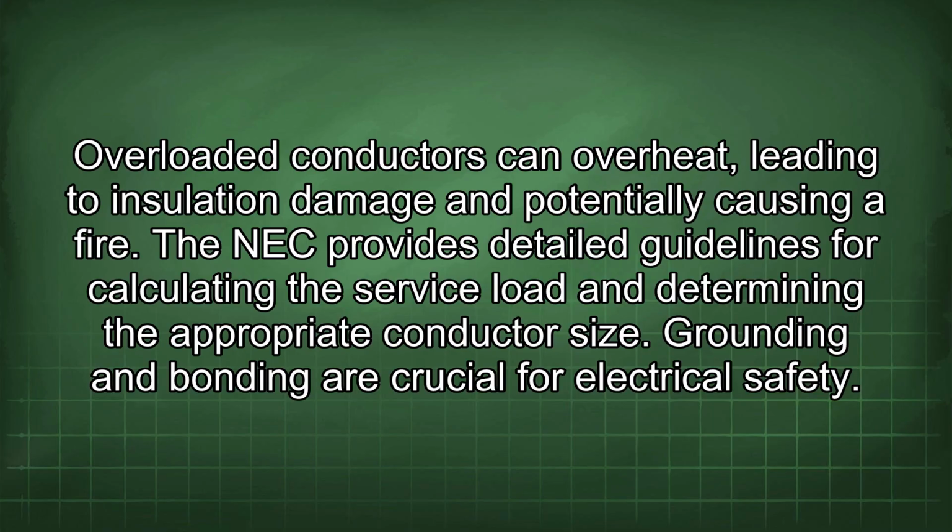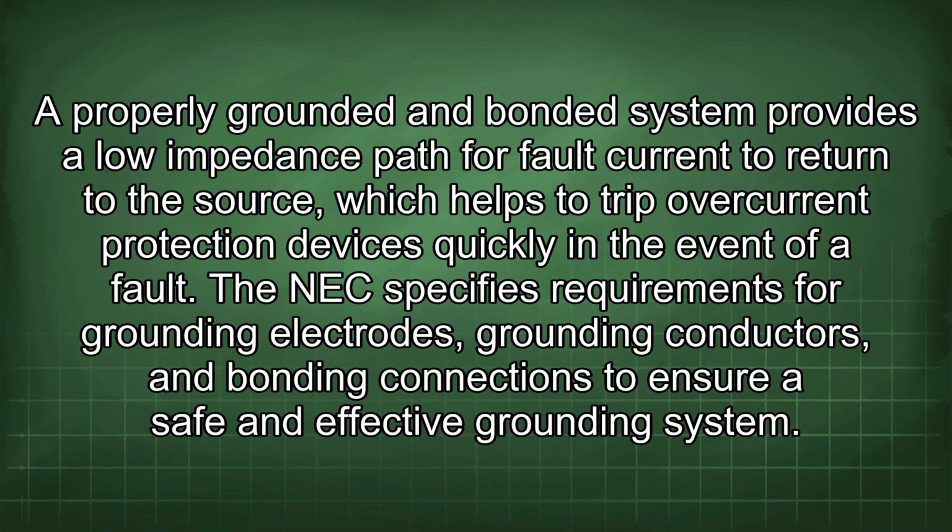Grounding and bonding are crucial for electrical safety. A properly grounded and bonded system provides a low impedance path for fault current to return to the source, which helps to trip overcurrent protection devices quickly in the event of a fault. The NEC specifies requirements for grounding electrodes, grounding conductors, and bonding connections to ensure a safe and effective grounding system.